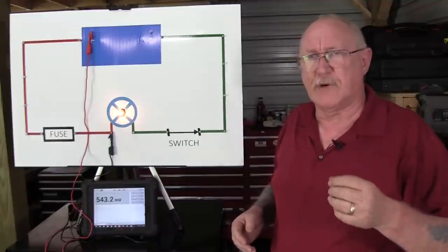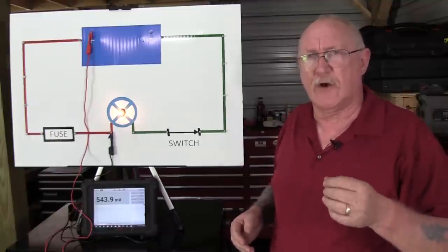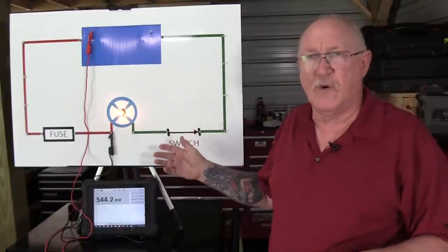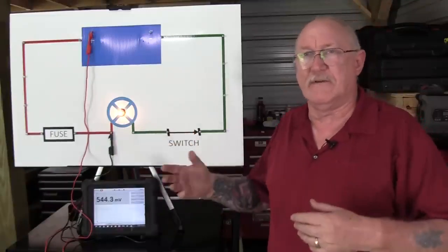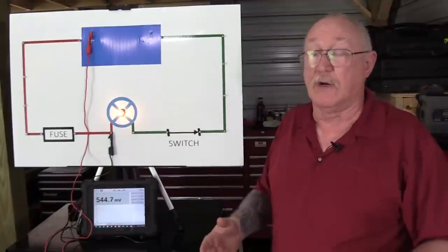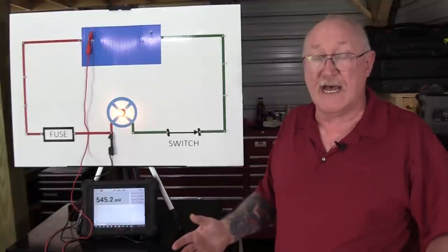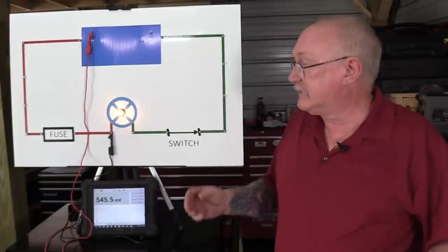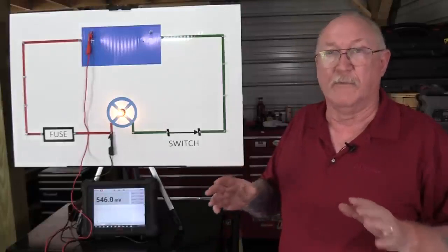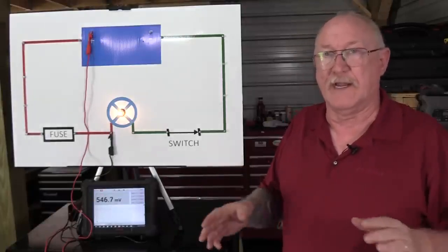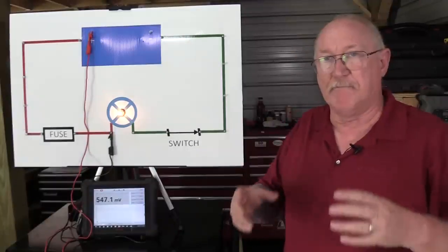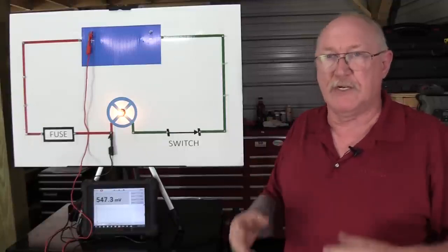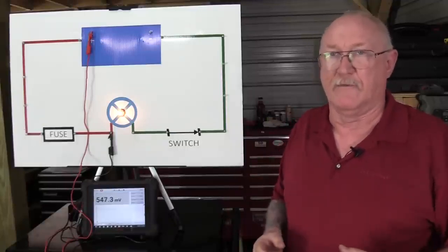If you're going to see a problem with voltage drop, you're going to see it like we saw it earlier. It's going to be 5.9 volts. It's going to be 1.7 volts. It's going to be a huge number, something that absolutely stands out and catches your attention. So don't worry about the little things, the little mice that are in there trying to get fed. Focus on looking for that big monster taking a big bite out of that available voltage.